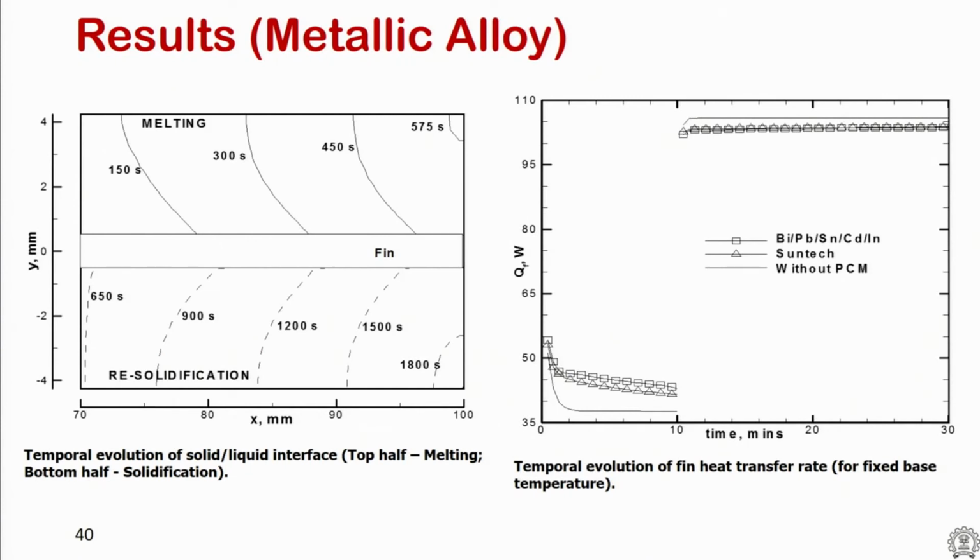To summarize, what we discussed in this module is that solid-liquid phase change materials are quite a good option, and lately they have been explored for battery cooling. What we will try to ensure for battery cooling is that the phase change materials offer a nice isothermal environment for the batteries, because the batteries need to be maintained within a certain range.